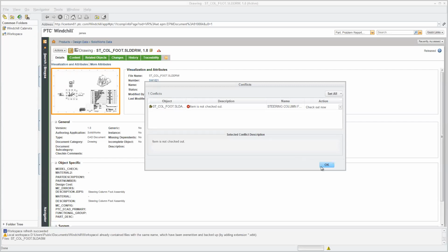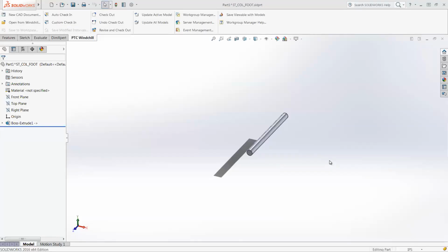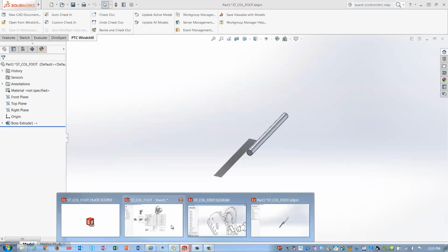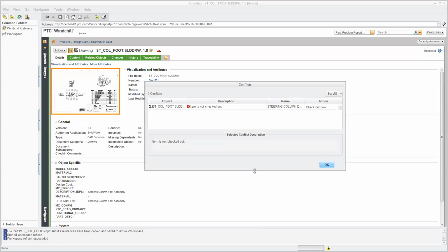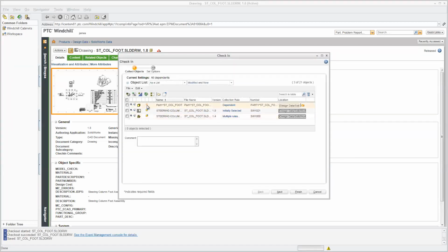So what it says is, in order to actually finalize those changes and push those to Windchill, you need to go ahead and do the checkout, go ahead, save everything. And then what you'll see now is even though I never did it to begin with, we checked it out, it automatically checked it back in, and now you will be able to see all of those changes pushed into Windchill. So it's making sure that as you're working, you're not skipping steps. Nothing's going out of line. You're following the process, you're following the standard, and everything's going to be controlled how it should be.